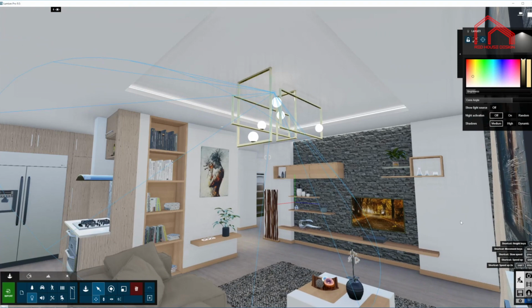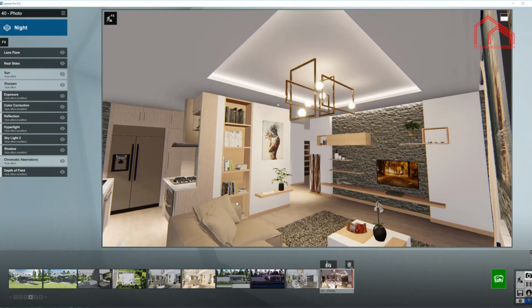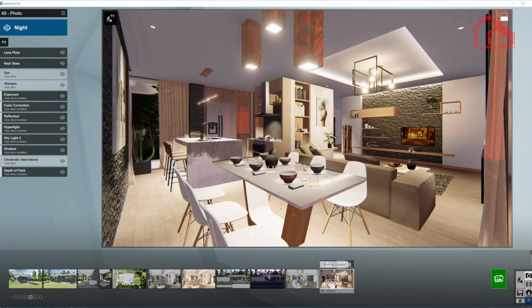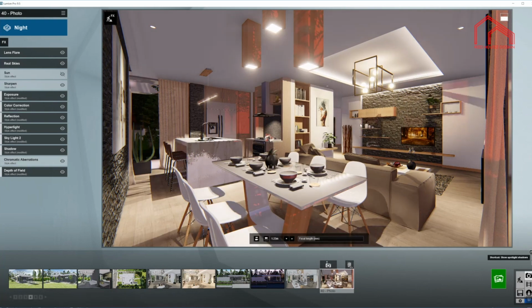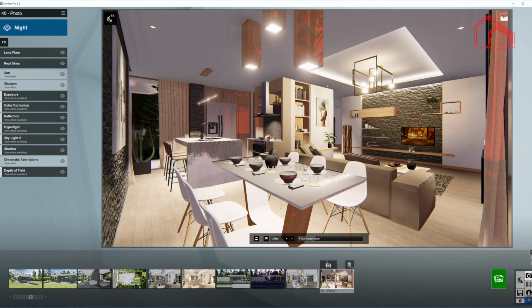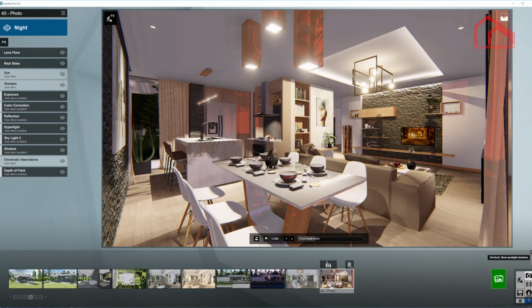And when we go back to our preset scene and I press the F8 key on my keyboard, once again we can see the difference. Now you can see the temperature of these lights is a little yellowish. It is warm, much warmer than these whites around it. And now you can see these shadows in here are not coming from these Omni lights that are on those bulbs, but they are coming from those 4 spotlights that I placed on top of the ceiling, just to be able to create the shadows in here from the table, from these metal structures on the chandelier as well.